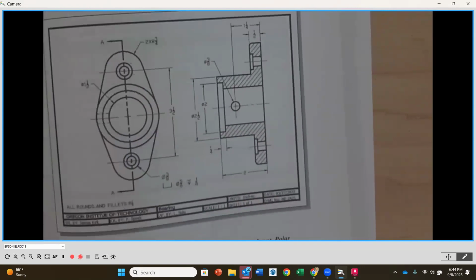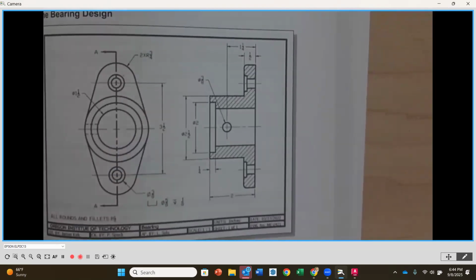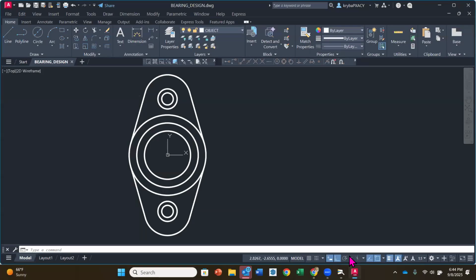Okay. So now we're really ready to generate our section view over on the right-hand side. Okay, so that's what we're going to do next. So as we look here in AutoCAD, I want to make sure that you have a couple things going. Number one, I want to make sure that you have the show snapping reference lines. It's the one that's over to the left of our running object snaps.